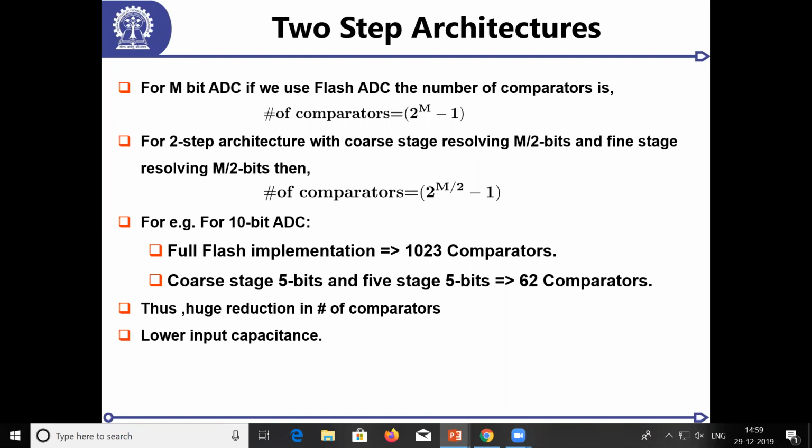I don't think I'll get into the details of this, but a delta sigma ADC actually gives you much more accuracy over a conventional ADC, but at the expense of the sample rate. The sample rate drops significantly. So again, going back to the nanometer ADC challenges, these are the different challenges which I've already talked about. I just put this slide in to come back to the nanometer ADC challenges.